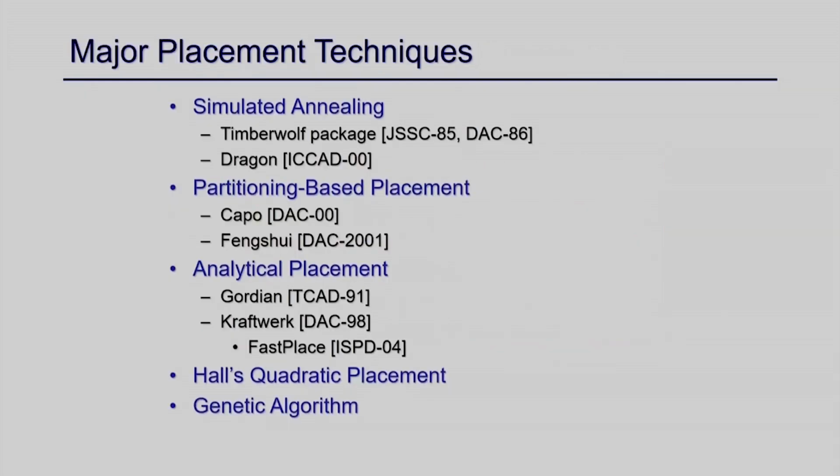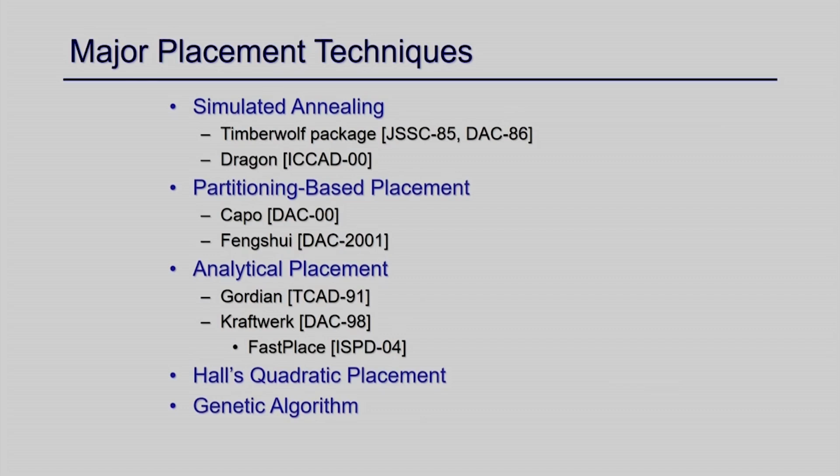Okay. So, in placement also, since it is another NP complete problem, you have various approaches like simulated annealing, partition based approach, analytical approach and so on. Again, I am not going to discuss the details of all of them, but the basic objective is understood here: just to reorganize your placement, I mean repositioning your blocks, so that you can reduce your total area and primarily total wire length. Okay. So, I will move on to routing now.